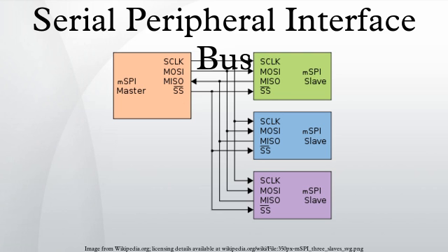Chip or FPGA-based designs sometimes use SPI to communicate between internal components. On-chip real estate can be as costly as its on-board cousin. The full duplex capability makes SPI very simple and efficient for single-master single-slave applications. Some devices use the full duplex mode to implement an efficient, swift data stream for applications such as digital audio, digital signal processing, or telecommunications channels, but most off-the-shelf chips stick to half-duplex request-response protocols.